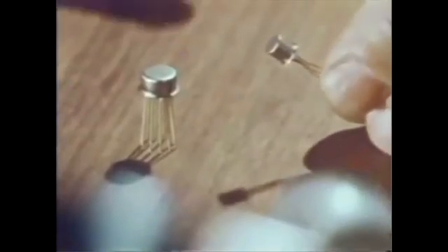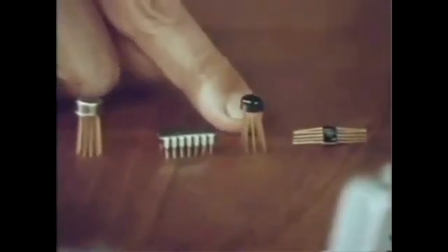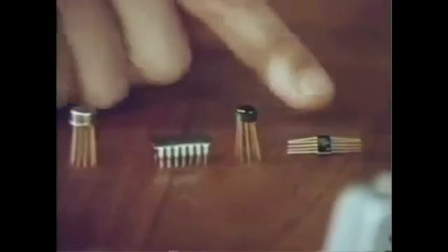In the old days, it was simple. You had a wide choice, two, large and small. A TO18 outline, small, and the TO5, larger outline. These days, we have upwards of 250 varieties of packages, and a user can select any one of them. Here are an example of three of these. A dual inline package, a plastic package, and a flat pack. The most nearly universal of these is the dual inline package. Let's take a closer look at just how that is made.